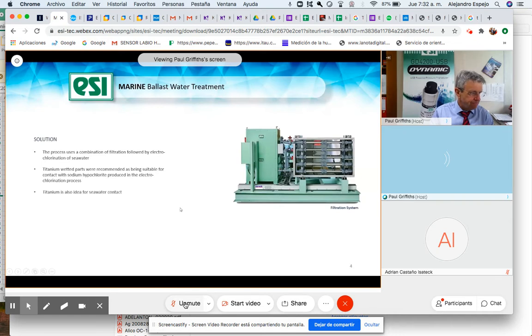So this is where our product, our GS 4200, and other products using silicon on sapphire come in. You remember last week we talked about silicon on sapphire, and it has a titanium pressure diaphragm that is welded to a titanium pressure port. So the liquid, the media, is only ever in contact with titanium. And this is perfect. It's not too expensive. It's quite a standard pressure transducer, but it has this excellent property of corrosion resistance.